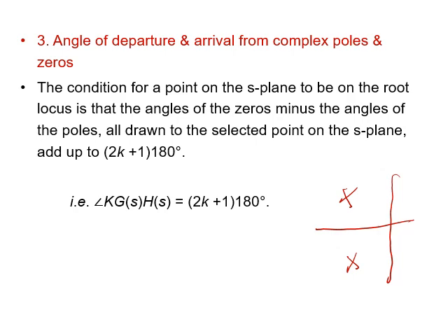Because if you notice here, this is the axis, so the line can start from anywhere on this 360 degrees. So let us say it starts at angle 120. That means here it's going to start. The root locus will start this way, then it will take its direction toward the actual root locus.